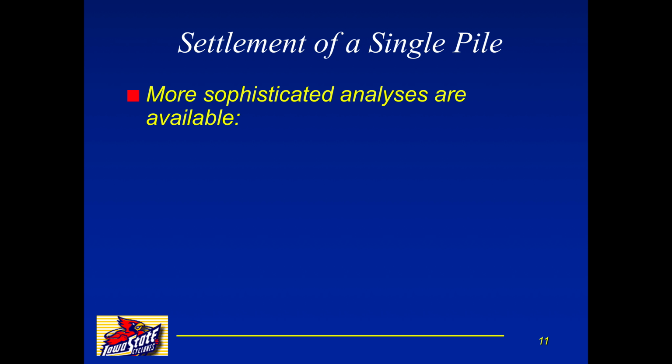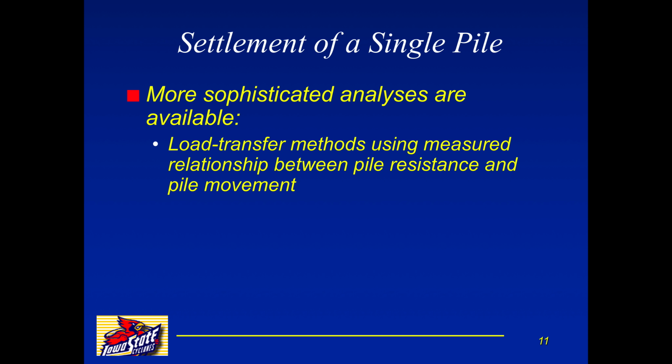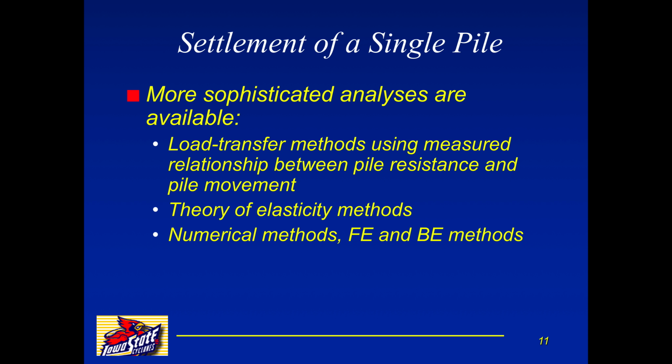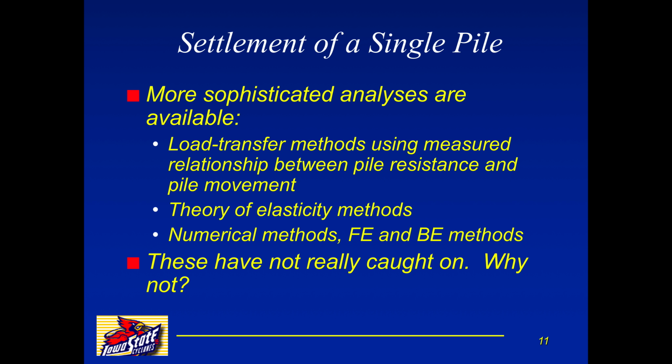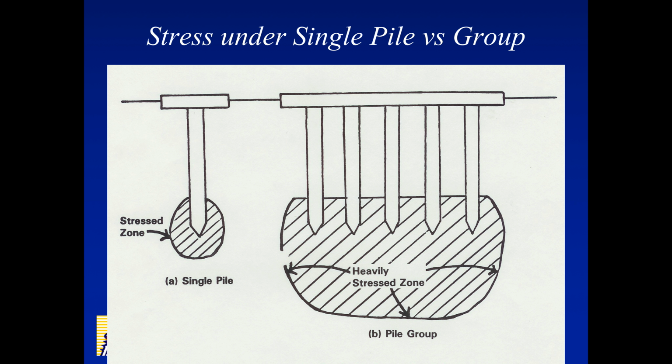So there are more sophisticated analyses available. You can use different load transfer methods using relationships between the pile resistance and the pile movement. There's also the theory of elasticity methods, and numerical methods such as FE and boundary element methods. But they haven't really caught on, because why? They're more expensive and time consuming.